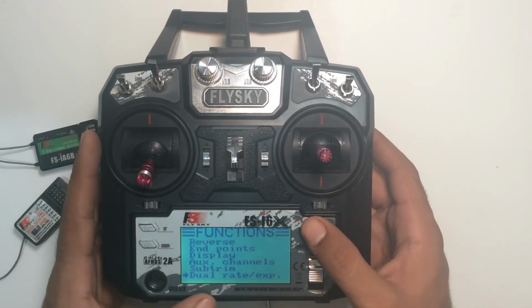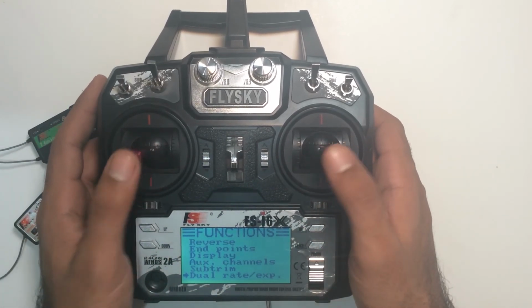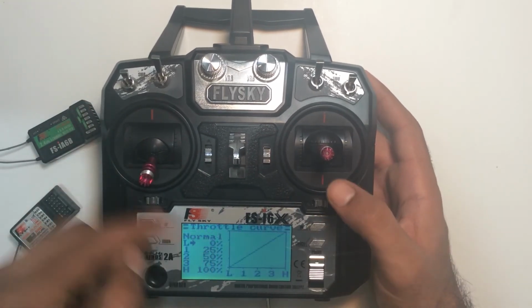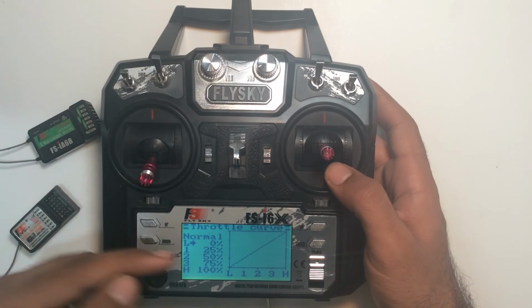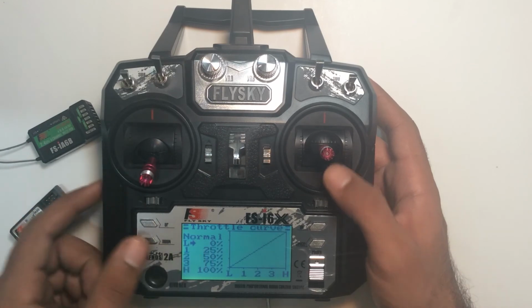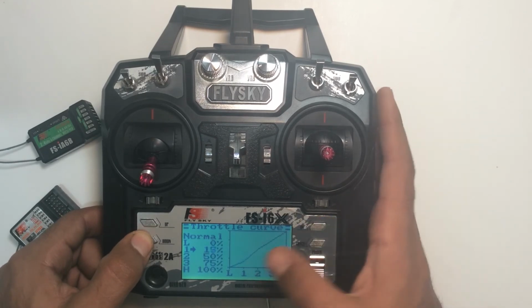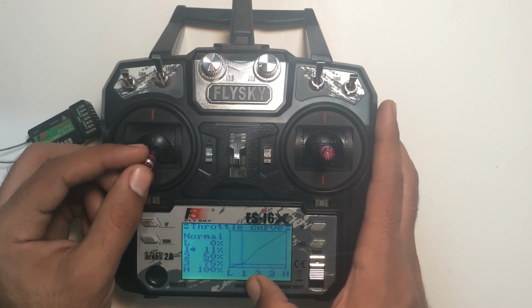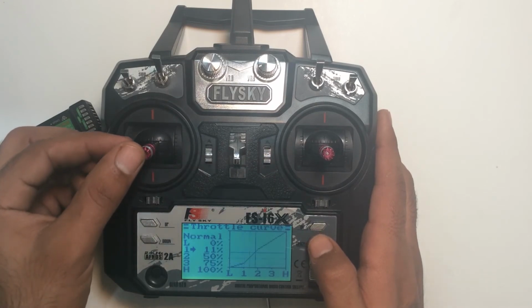The next one is the dual rate and exponential settings, which is actually the sensitivity of your controls. I'm going to explain it in detail in a later video. The next one is the throttle curve. It means how much your throttle increases upon stick movement. For example, if you want your throttle to increase less from 0 to 25, you decrease the value of 25, and the graph will change. Your throttle will be increasing less, and then your throttle will have more ratio of increase.